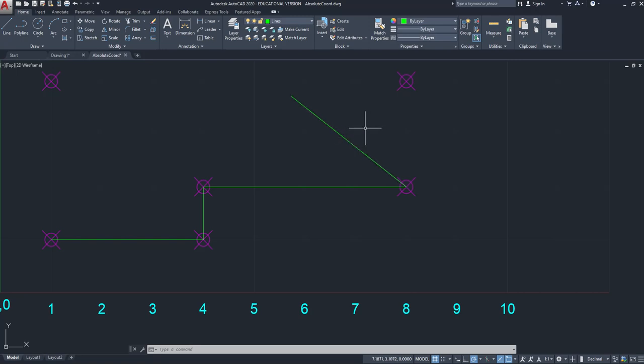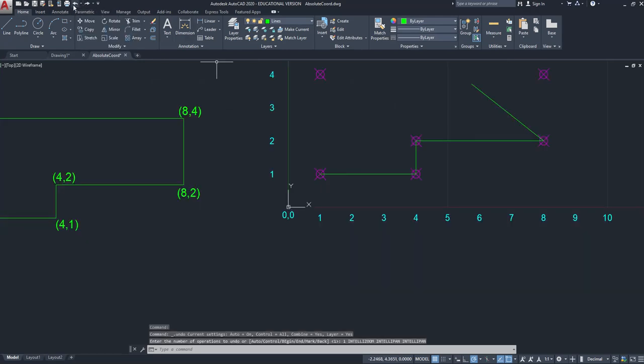Okay, there's a couple ways. If this was the last command that I had done, I can hit undo. Undo on the keyboard is Control-Z. I also have the ability to come up here and click undo right here. So click, it undoes it. The undo works consecutively, and it backs up. So I can undo a lot of commands up until it has saved. If it's saved, it will probably stop the undo command right there, like it won't let you go back past a save, but I can undo several commands to get back to where I needed to be.